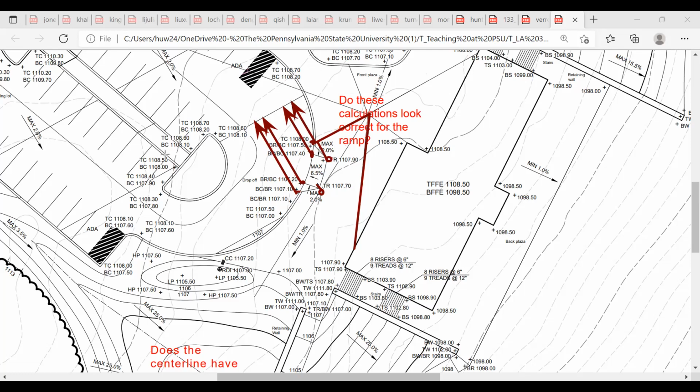Yeah, I think so. Sorry. I think I calculated the spot elevations correctly, according to what you said. So then to find the slope, I did 0.1 for the difference between the two spot elevations, and then divided by the distance, which was 5. And I did get 2%. So I don't know, you said that's wrong?